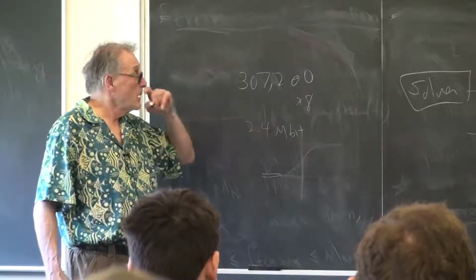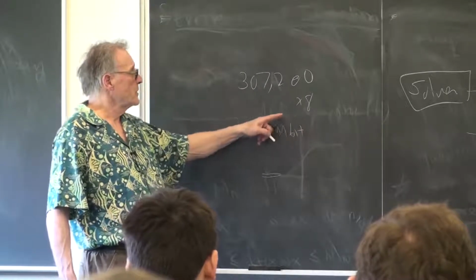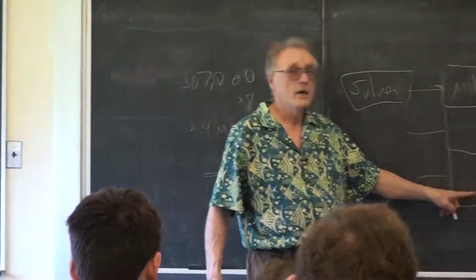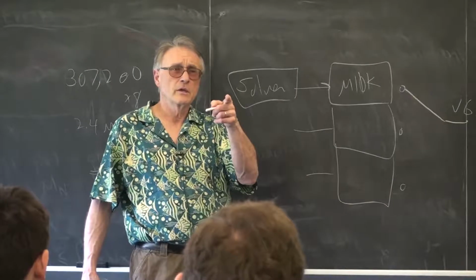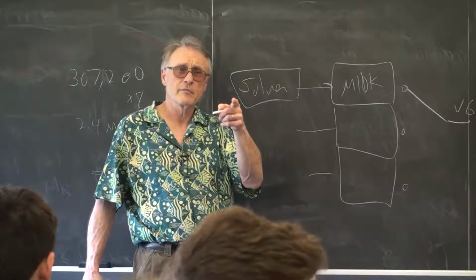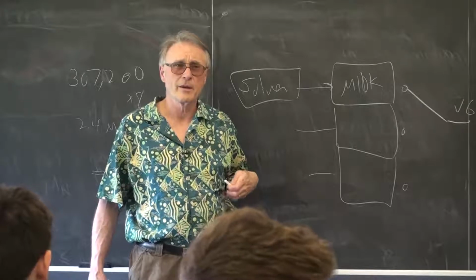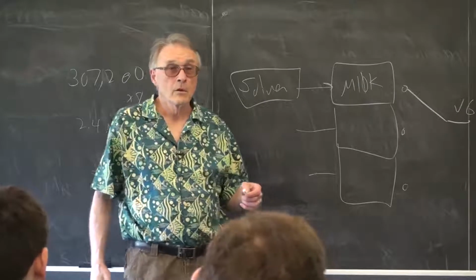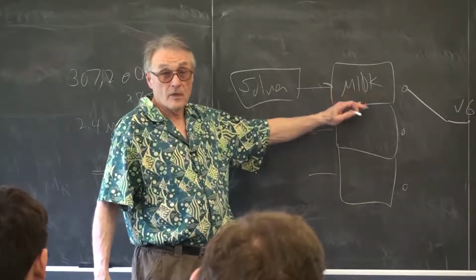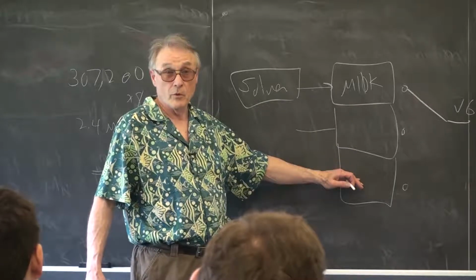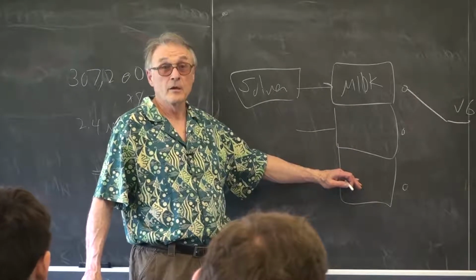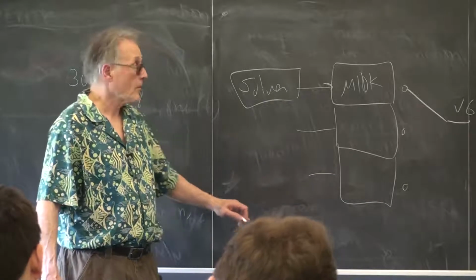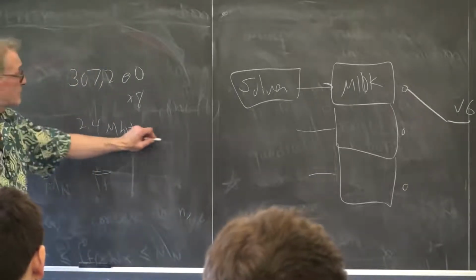So let's say that you should be able to do M10K blocks on full color. But Istvan, did you have a problem with that? Did you run out of memory or something when you were trying to do that? Do I remember that, or am I making that up? Because it only used 11 or 12 colors. We have 4 bits. So you coded this as 4 bits. So you were in fact using 1/4 of the onboard memory to do the update. But even if you'd gone to 8 bits per, you could have fit it in, I believe.